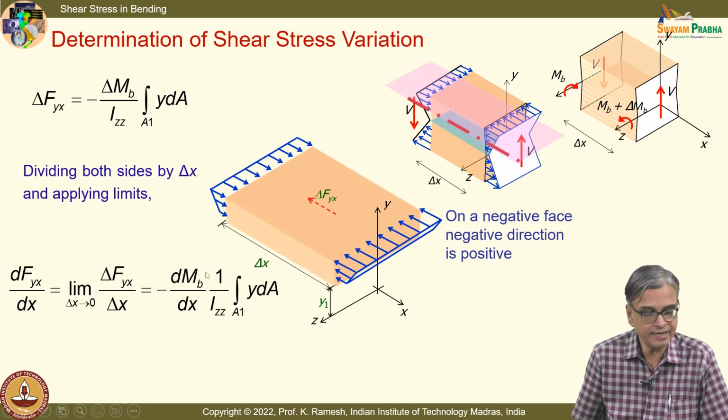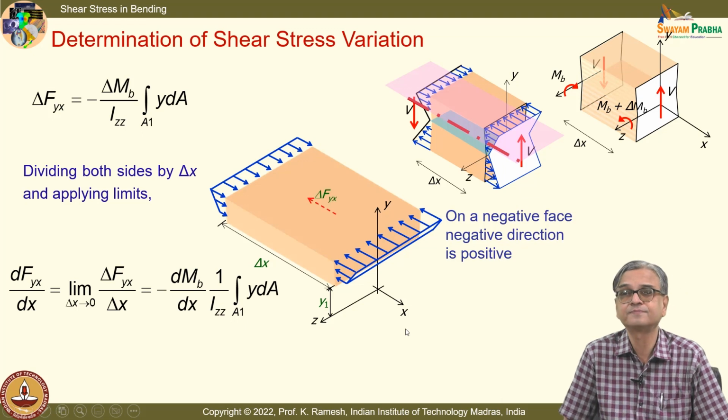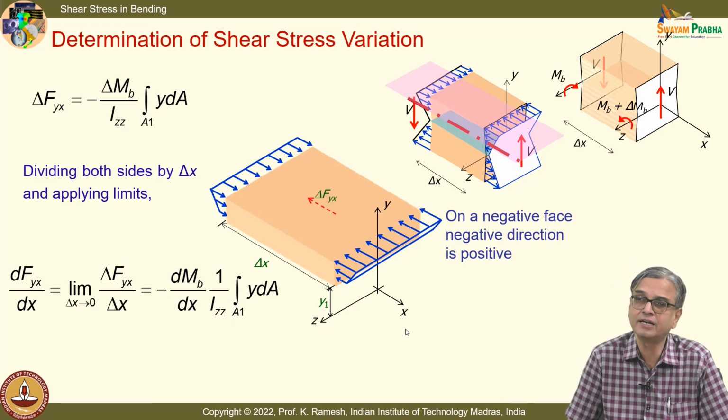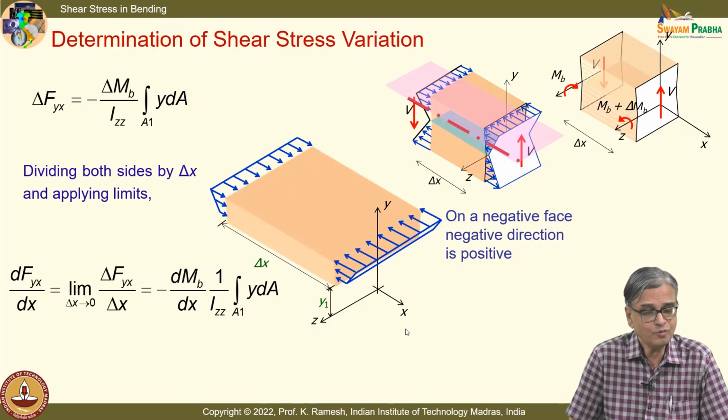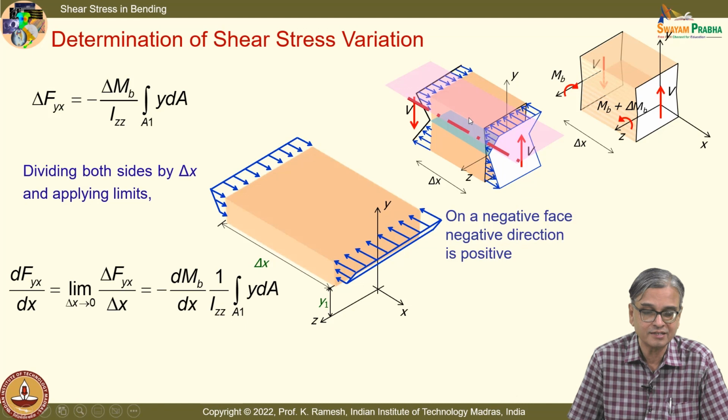Can you tell me how I can bring in the shear force here? Is there anything that you know from your earlier development of the subject? You can be louder. Equality of cross shears we have discussed, that is one idea, because what she is trying to say is, if I have stresses developed at the bottom surface, I should have stresses developed in this surface also. So, if I have this as x plane, I will have tau xy developed, and by equality of cross shears, whatever tau xy is developed, I will have tau yx, that is fine.